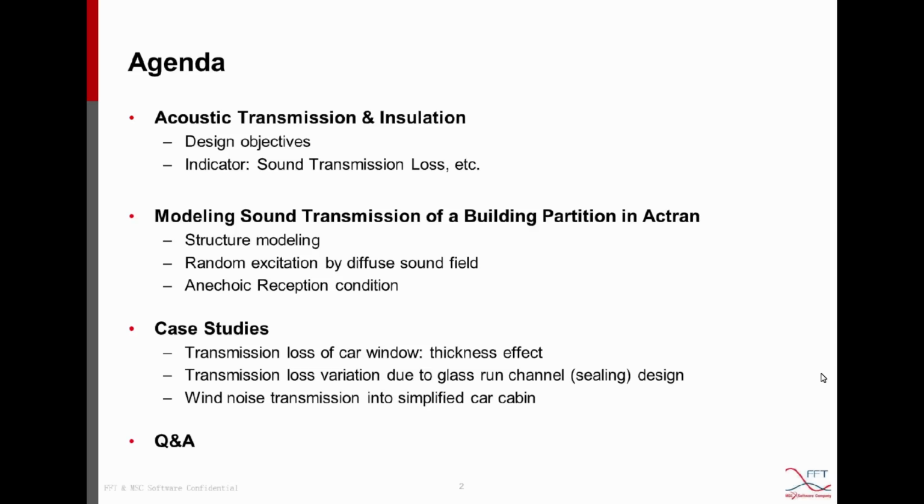Then we will walk through a modeling process in Actran to simulate the sound transmission of a building partition. I will demo live the modeling of the structure, applying the random excitation of a diffuse sound field on one part of the partition and getting the transmission on the other side of the partition to calculate the sound transmission loss. And then we will review several other case studies on the topic of acoustic transmission.